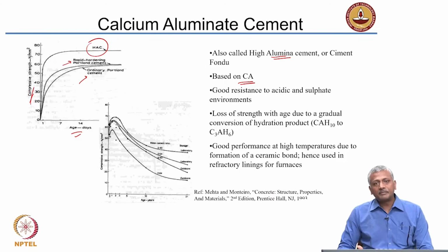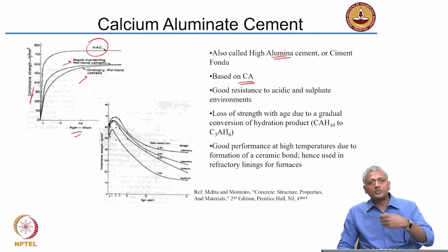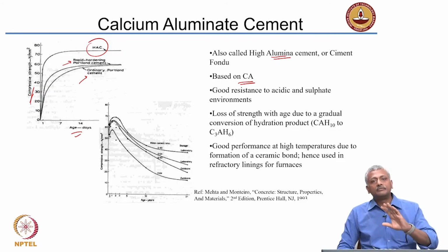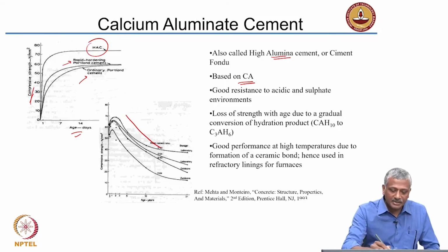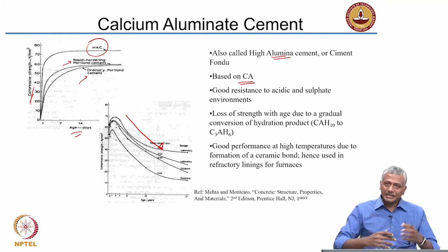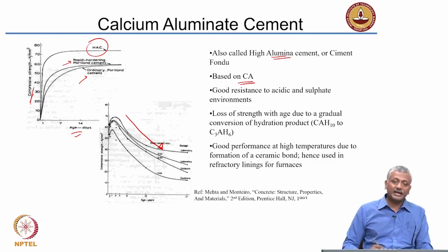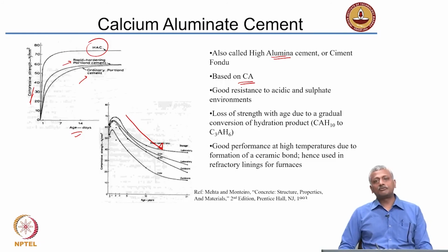Right? So they started developing a lot of structures with high alumina cement, which gained strength rapidly. The problem was, as the concrete made with this cement was exposed to the external environment with moderately high temperatures and humidity, the strength basically dropped over time. This happens because of an internal chemical compound composition which changes as it is subjected to continuous exposure to temperature and humidity. Because of that, you have a problem using the cement for normal construction.